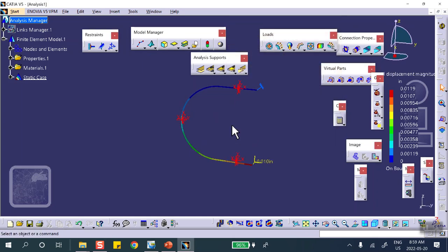There we are. Okay. Now you might ask yourself, and we did talk about this yesterday a little bit, why do I bother doing this? It took more work trying to put these points and lines in. Can I not put it in the sketch? The answer is yes. But if your curve is not fitting in a sketch, meaning fitting in a plane, you can't put it in a sketch. If the geometry in the space looks like this, there's no way you can put this in a sketch. You have to do it as separate entities, splines or lines, etc.